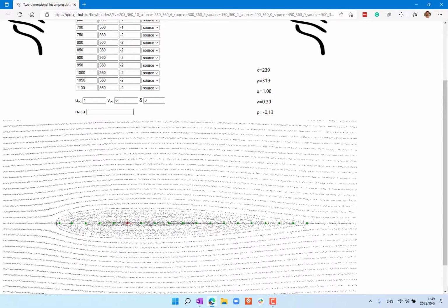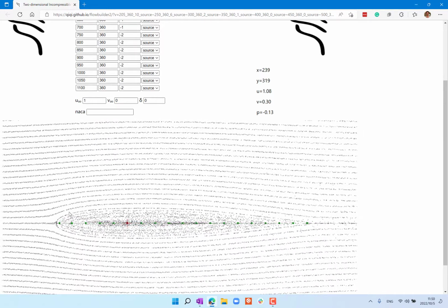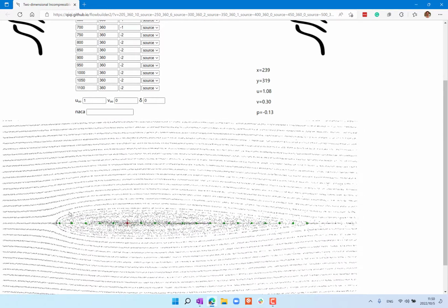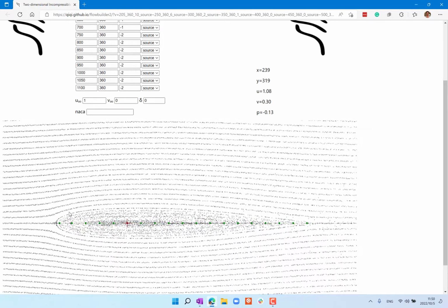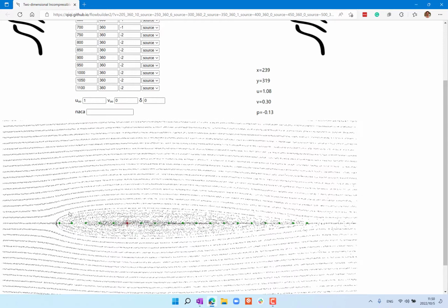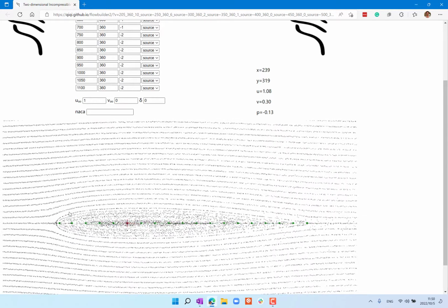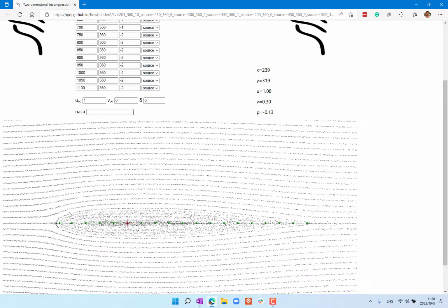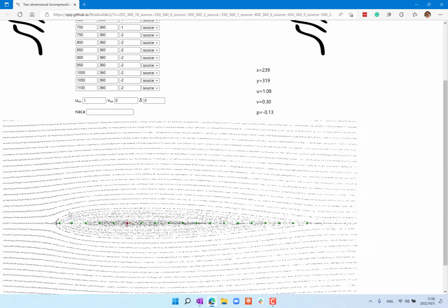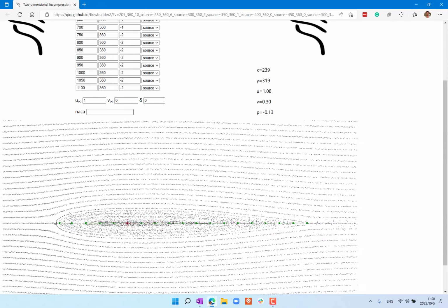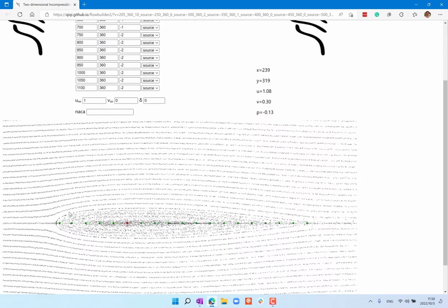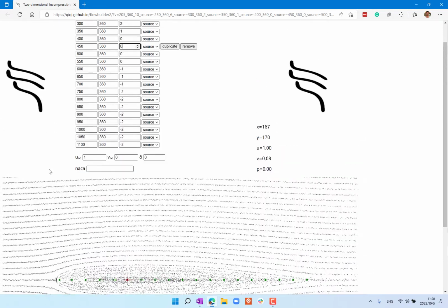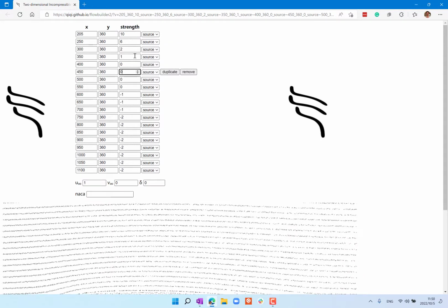Now, what is the effect of increasing that source? It increases the thickness. It increases the rate of thickness increase near the leading edge, right? It makes the leading edge even fatter, less sharp than this one. So basically, I get a whale-like airfoil if I want the peak suction near the leading edge to be large. So let me just make a whale-like airfoil.